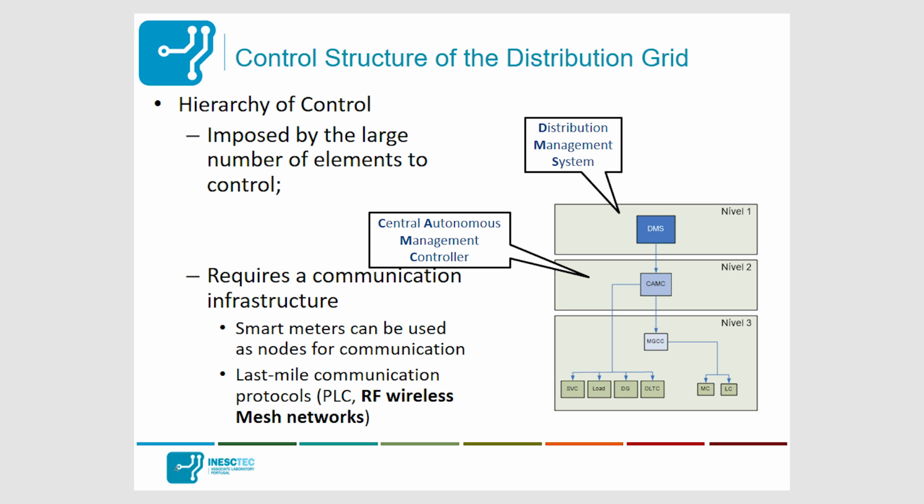And this establishes communication links with the microgrid central controllers that are housed at the level of the microgrid, and of course, the microgrid communicates with the controllers of the microsources and the loads. And of course, at the medium voltage network, there are also communications with the DG units, with the online tap changing transformers, with the capacitors, and so on.